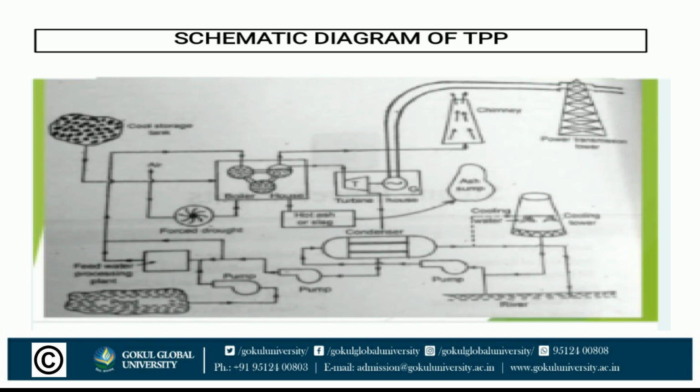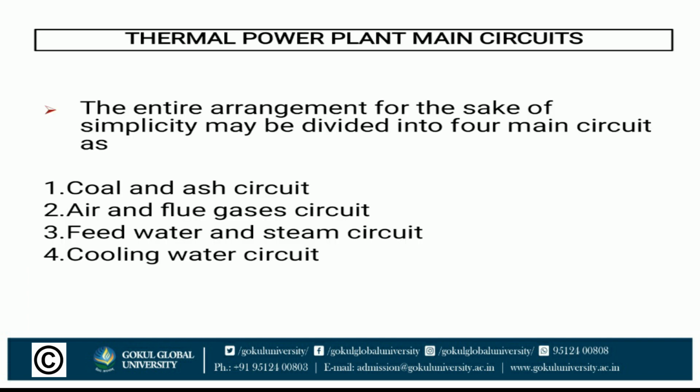Ash is the product of coal combustion in the furnace. Along with flue gases, about 20% of the ash falls in the bottom ash hopper of the boiler and is periodically removed mechanically. The ash from the hopper is removed to the ash storage by means of scrape conveyors, then goes to the ash handling plant, and is further sent to the ash disposal arrangement.